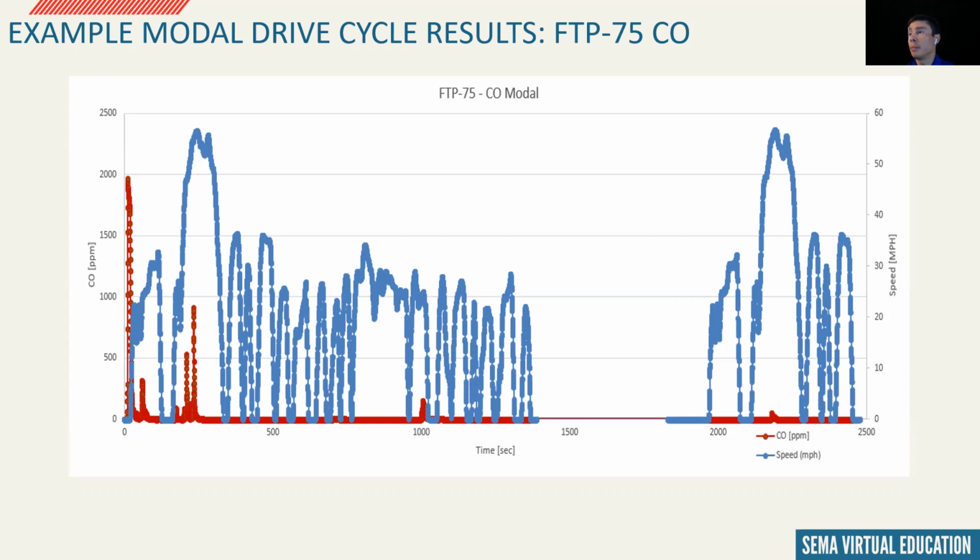Sometimes power enrichment calibration can be skewed because of poor torque mapping or because we're relying on power enrichment to reduce spark knock, detonation, because of high boost or advanced ignition values. Be mindful of this. Also, when COT thresholds are not calibrated correctly or airflow and load are not modeled correctly, we can have catalyst overtemp enabled too early, and this could cause high CO emissions.